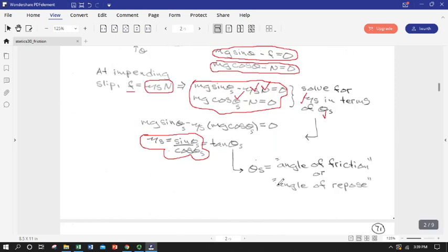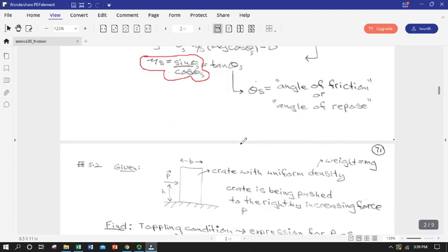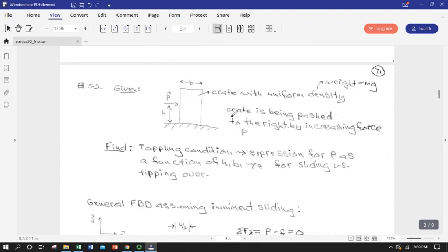So this angle is sometimes known as the angle of repose or the friction angle, and it is literally another way of expressing mu sub s. So the tangent of the friction angle is a way of expressing a coefficient. Somebody can say, what's your coefficient of static friction on that ramp? Or they can say the tangent of the friction angle is, and give a number. Notice they're both unitless. That's an important consideration. That's a good way of telling you that you didn't make a math error.